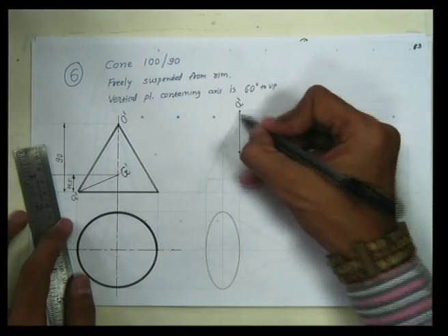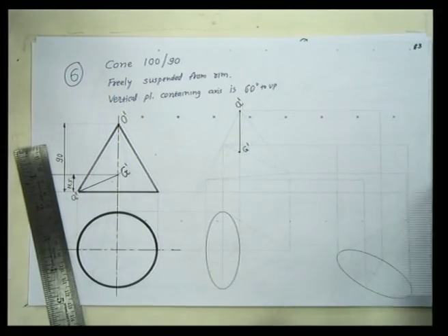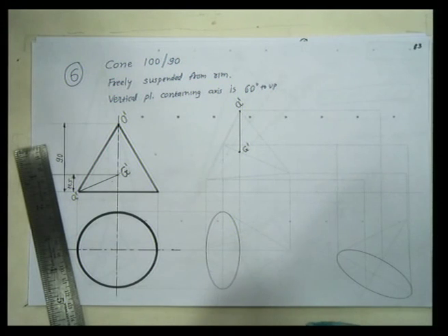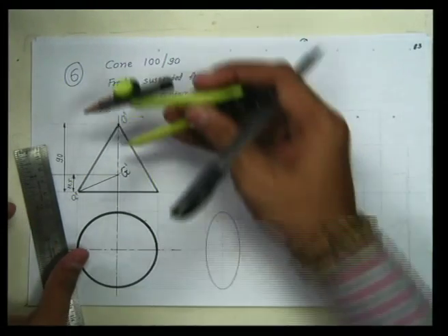Now we have located 2 points, and by taking the distance from these two reference points, or by measuring distance with the scale or by drawing arcs, we can transfer rest all points like this. O dash is here,